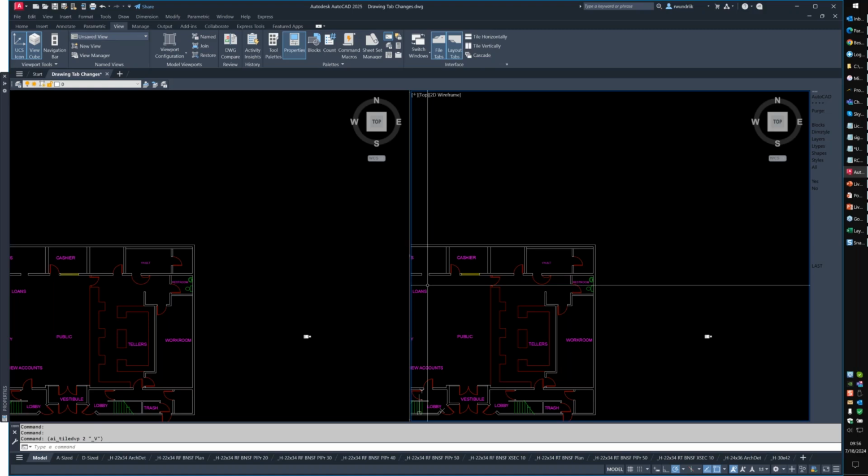I've seen that. It also depends on how far away you are from 0, 0. Sometimes I've seen that scenario if you're far away from 0, 0. Now, Tim, I know you're in Civil 3D most of the time, so I know that we civil people tend to not be anywhere near 0, 0. But that's something you and I can have a discussion about, and you can show me if you've run across that again. But that's usually where I find it. It can be a calc problem.